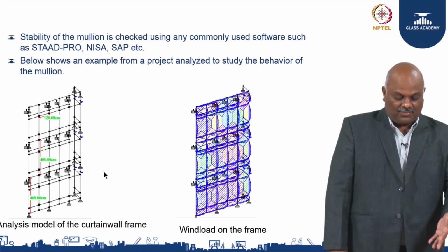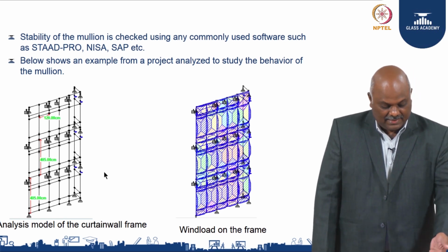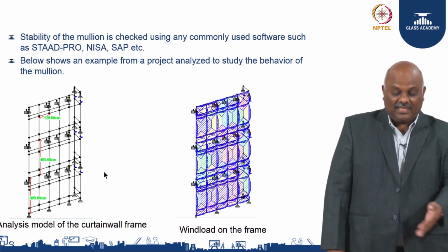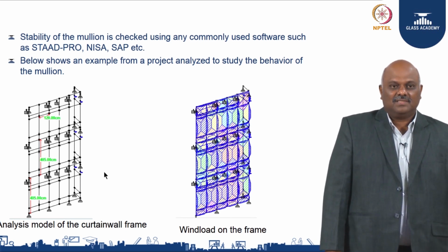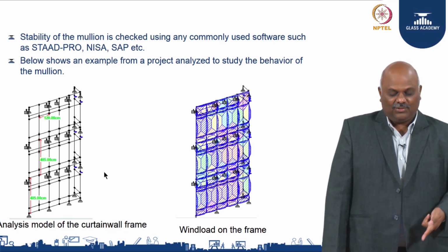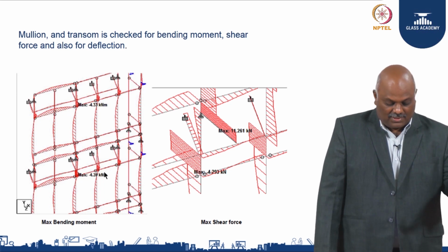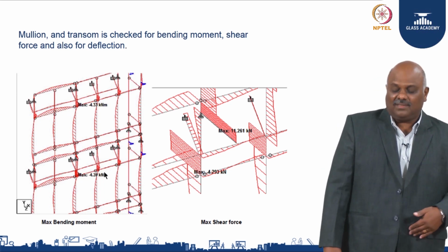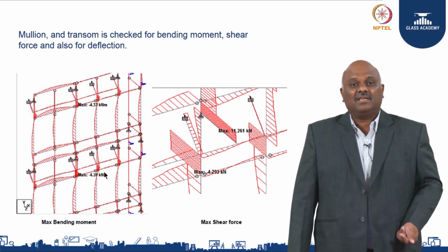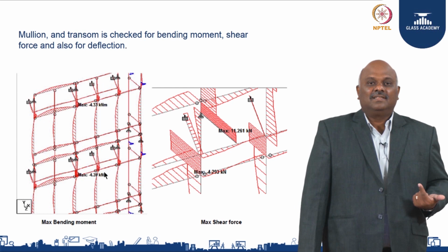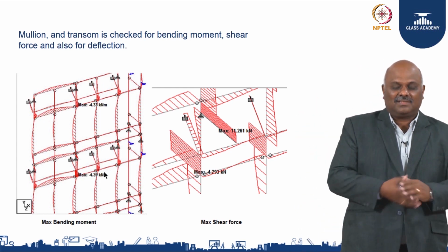This is an example shown for a building with floor-to-floor panels anchored in 2 places, and how they react is what is shown here. So, you check the substrate first, check the bite thickness, design your mullion and then you check your mullion. In the mullion, of course, you check all the required factors. Most of the time you check your mullion for slenderness and deflection. If the mullion deflects more than the allowable, then the whole thing will collapse or start to deform.